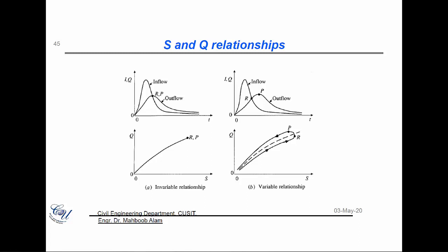Fine. So you do not have a particular relationship between the decrease in the depth and the outflow. In the initial case, for every 2 meter reduction in water surface, you always have a particular outflow associated with it. But in this case, even if the reduction is the same, for example 2 meters occurring at one time and 2 meters another time, the outflow would be different.